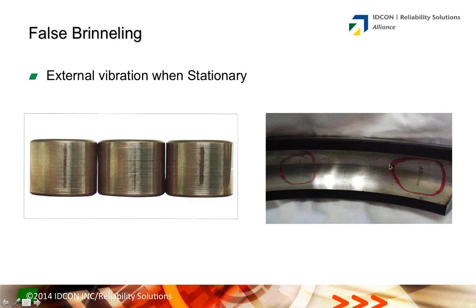Now this again is a ball bearing. The fact that that damage is centered on the race tells me that that damage was done in service while this machine was on standby and not operating. Many people store their bearings flat. So if that damage had been done in the warehouse, I would have expected to see the damage down here on the side of the race. So again, the marks tell me what causes the problem. Their location tells me why.